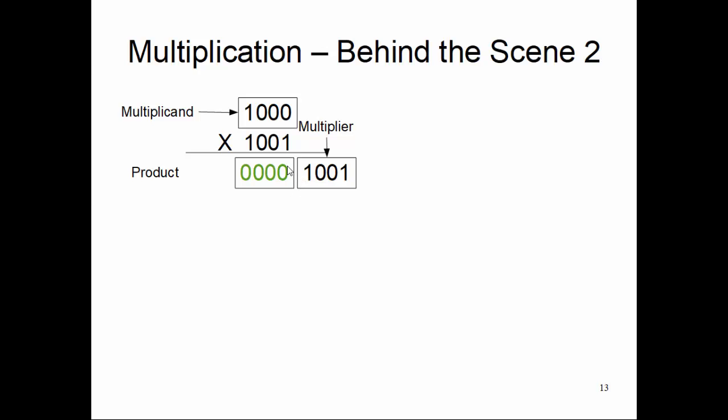They are connected in hardware in such a way that if we apply shift to both of these 4-bit registers, the left-hand-side register's LSB will be reflected into the right-hand-side register's MSB. So we arrange the hardware in such a way.